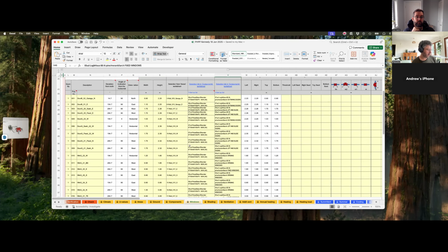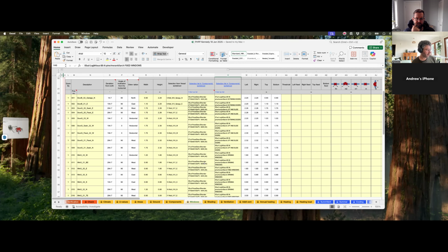Windows are all in, the Logic House windows. Yep. So we have to assign to the different types. So we've got outswing doors, lift and slide, opening window, fixed window. So they're all assigned from the schedule. There's a few different glazing units to match. For example, the lift and slide is a 54 mil unit. Everything else is 44 mil unit. So that's all in there.